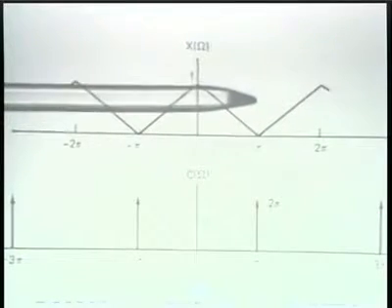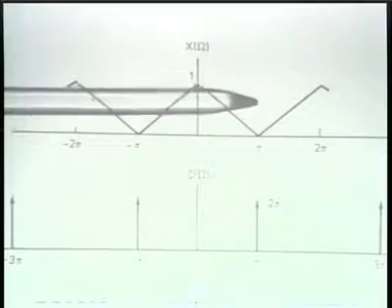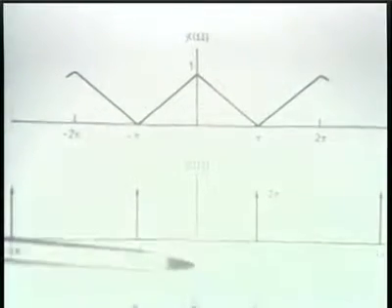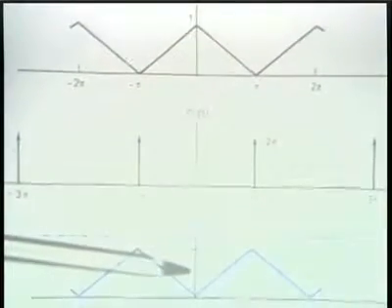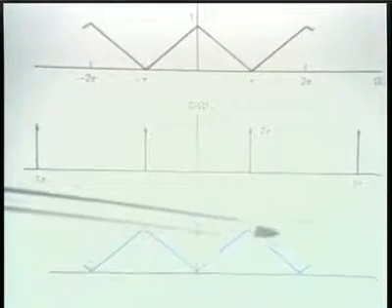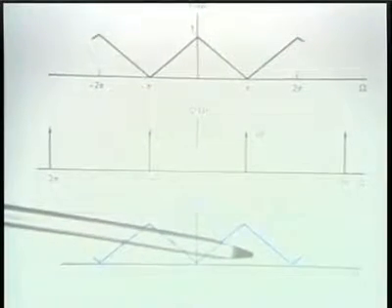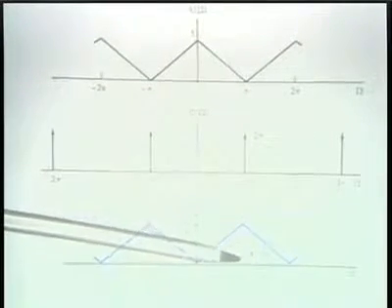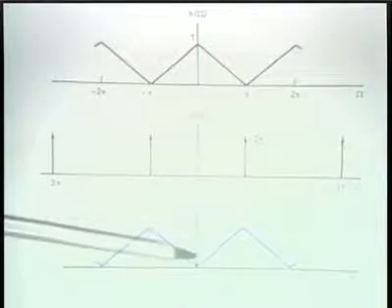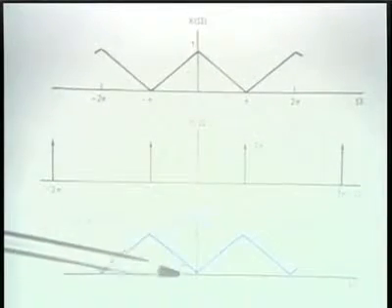And so after modulating, the result is a shift of that spectrum so that what happened at low frequencies now happens at high frequencies, namely around pi, and what happened at high frequencies now happens at low frequencies.